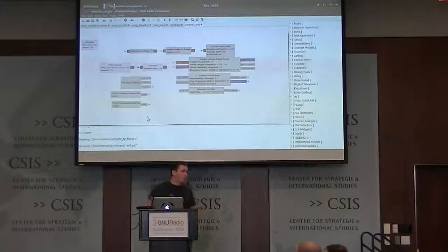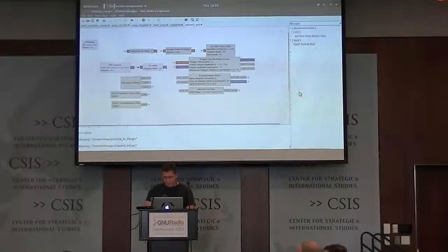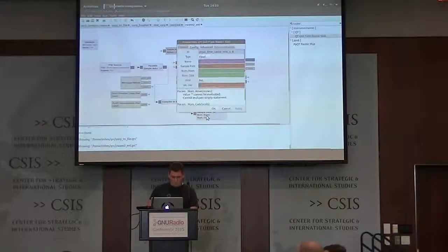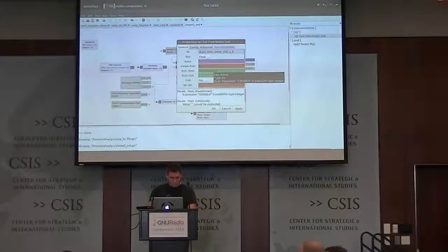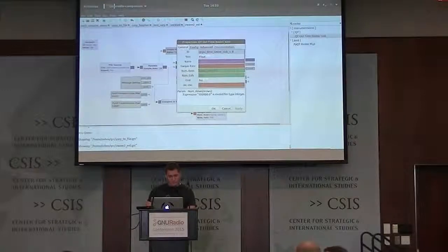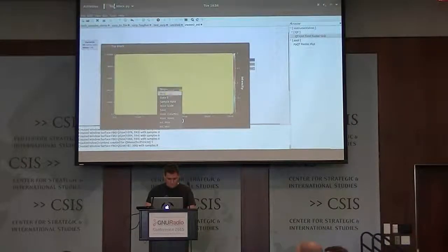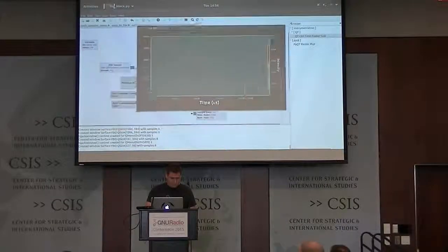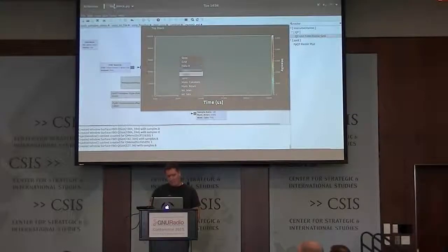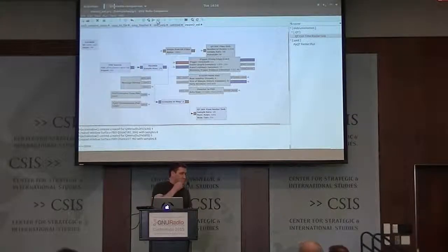PyQt has its own one, which does the same thing, but it rasters a message at a time instead of a fixed number of samples. So if we put a time raster sink here, put it on the magnitude, for example. Alright, is there a file issue? Okay, well, we won't do that now. But there's a raster plot for both streams and messages.